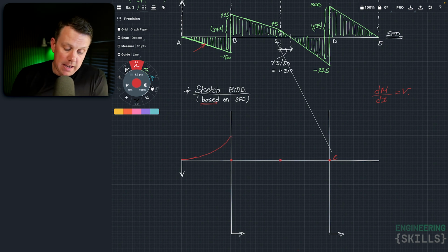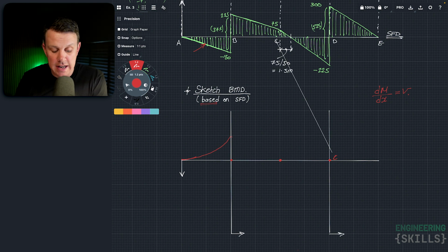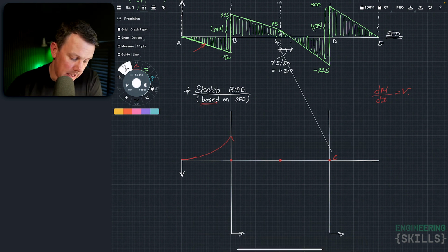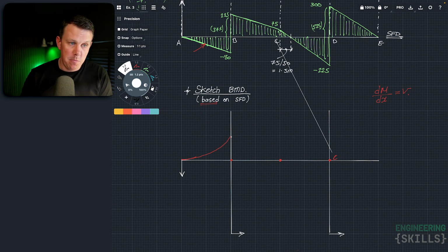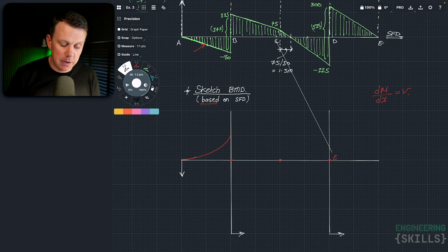So going back over to B, just to the right of B, the shear force immediately goes through a step change and becomes positive, right? So we know that it's going to be sloping in the opposite direction now. So it's going to be sloping like this, but it's going to have an even steeper slope. I will say, because we now have 4 elements framing into the same joint, not just a beam on one side and a beam on the other side, meaning the moments have to meet. It means the moment on the right hand side would have to be the same as the moment on the left. We don't have that anymore because we have beams framing in and columns framing in,